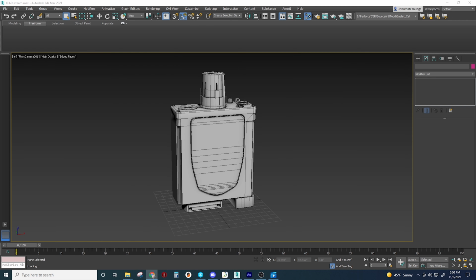Next, we need to verify the scale of our object. A quick Google search of a JCAD led me to find its real-world dimensions are roughly 7 by 4 by 1.5 inches. So I will use the measuring tool to verify the model's dimensions and scale the model appropriately. Ideally, the game model would have been modeled at the correct scale, but we can double check that and fix it at this stage so we know the game model and printed prop will be 1-to-1 scale to each other.